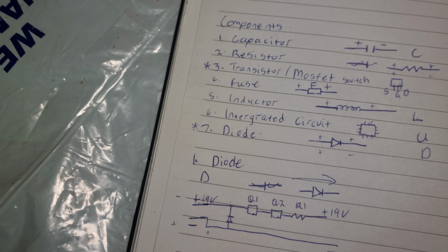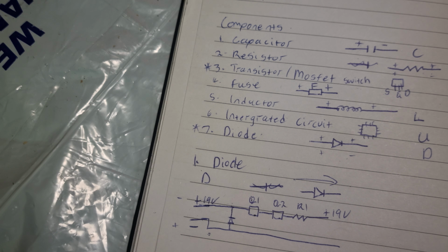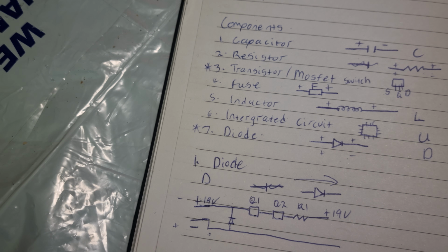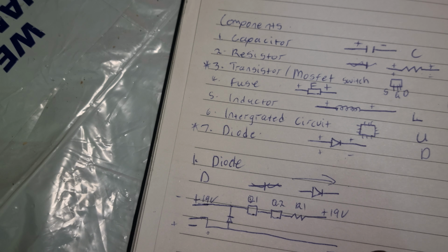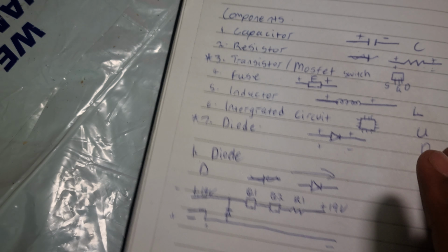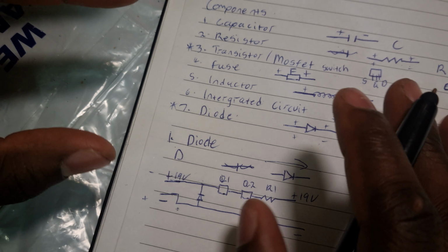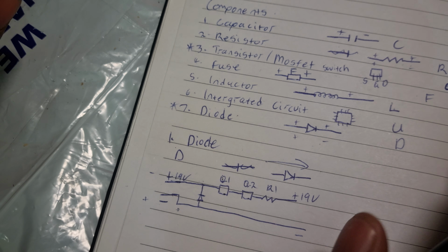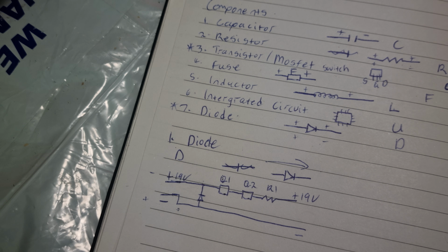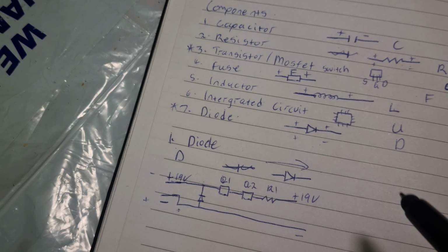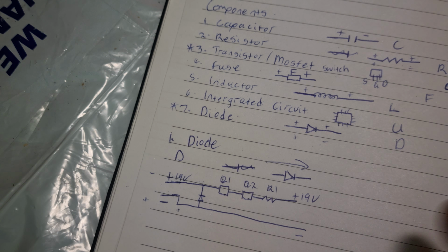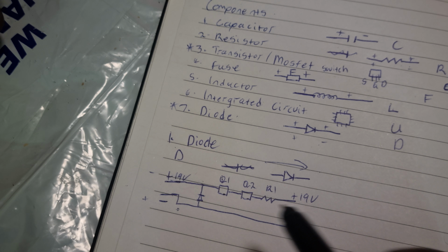That's the whole idea behind this. Most of the time, those chargers have protection circuits in them, such that if you plug in and there's a short circuit, it cuts power. If you remember, you've got chargers that will switch off the power light. The charger's LED indicates that it's powered on, but when you plug it into the laptop, it switches off. That's a mechanism designed into chargers, especially original chargers, that cuts off if there's a short circuit on the output. So yeah, that's pretty much the application of a diode.